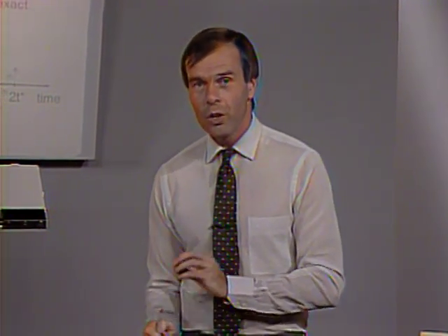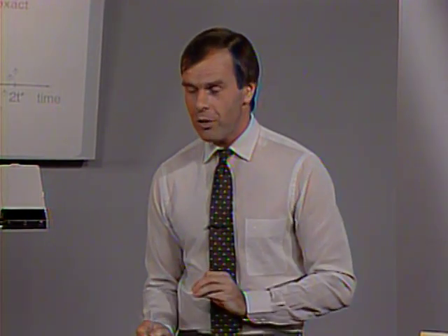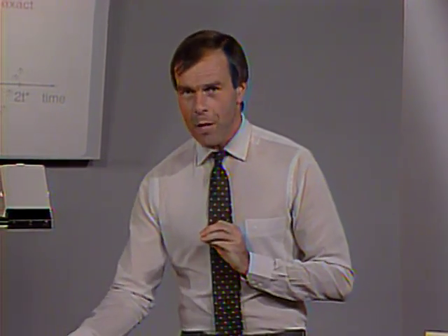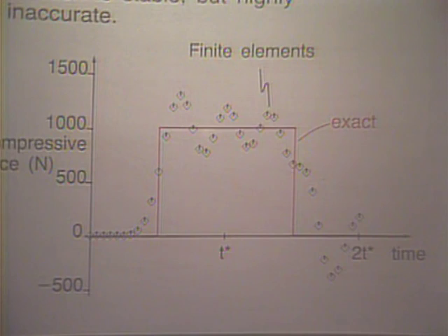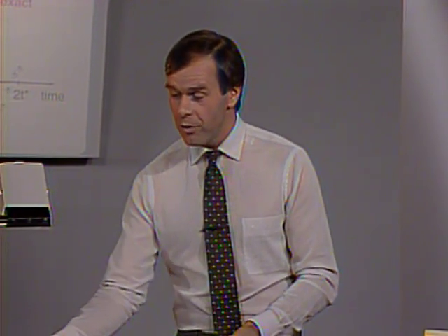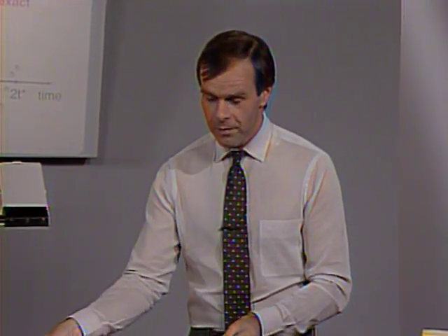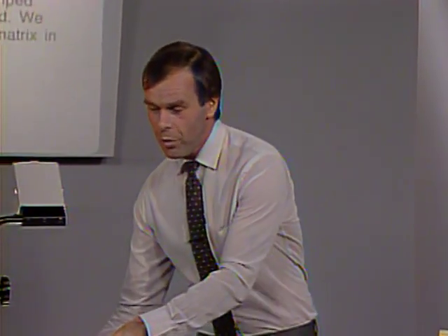Well, it turns out that using the explicit time integration scheme for this type of problem, this wave propagation problem, with a smaller time step, more cost, higher cost, you get worse results. That is really something to keep in mind. Now let us consider the trapezoidal rule.